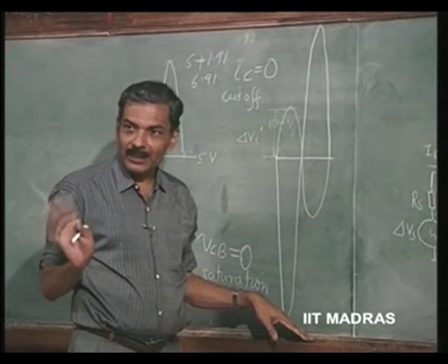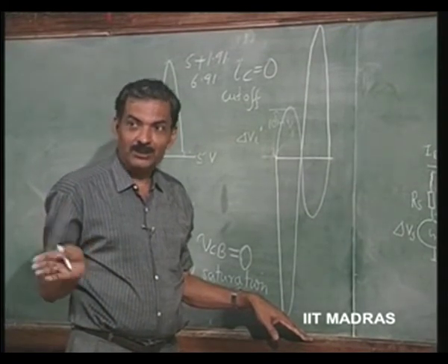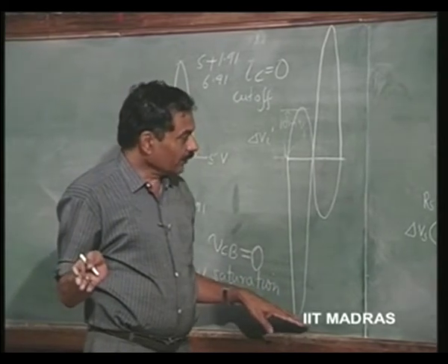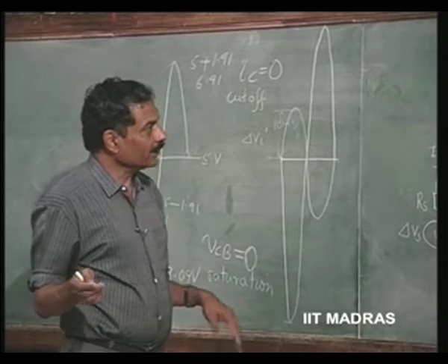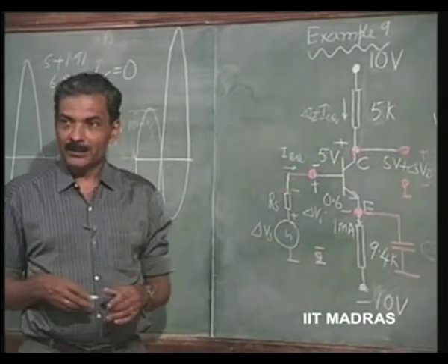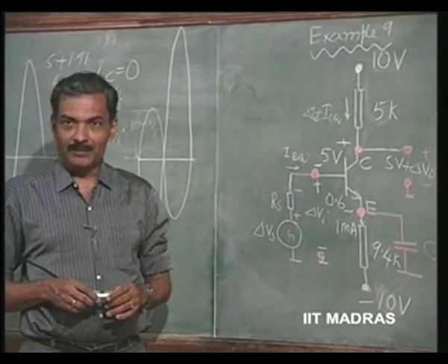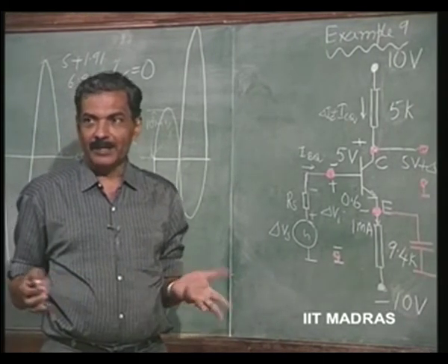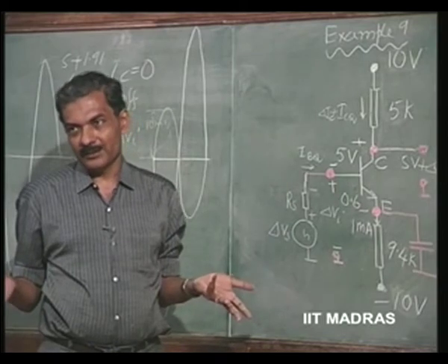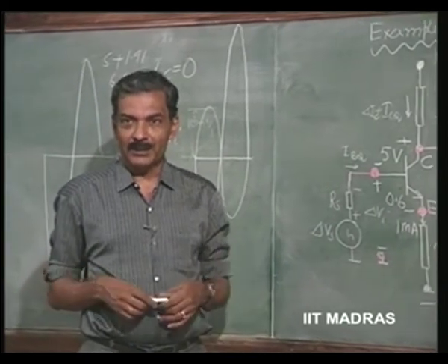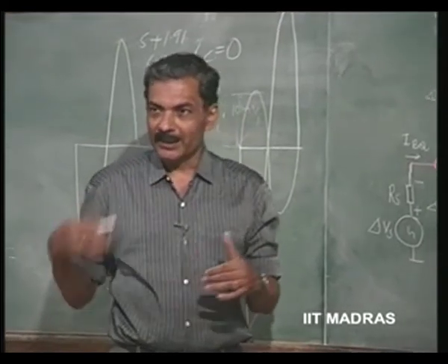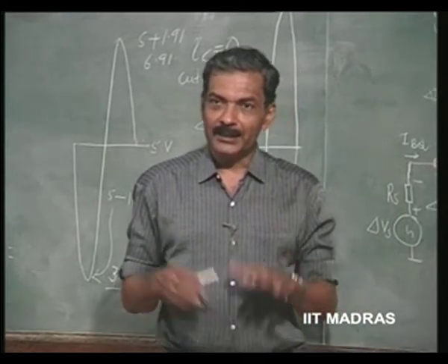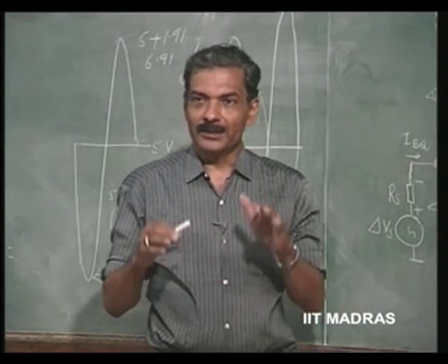The waveform will not look like a sine wave any longer because of the non-linearity of the amplifier. So, you can always locate the operating point in such a way that this symmetric swing limits get reached, if you are amplifying sinusoidal signals. If you are amplifying some other type of signal, then depending upon the positive and negative going signal, you can accordingly select the operating point, so that it is all the time in the safe range of operation.